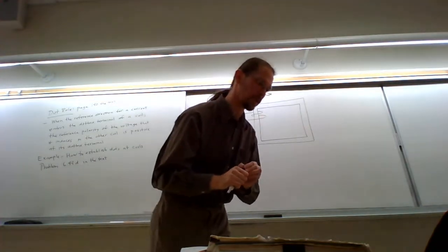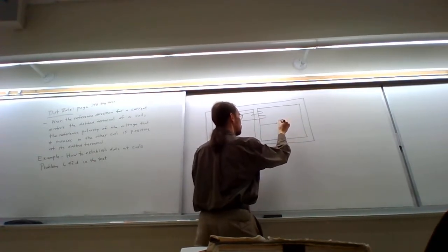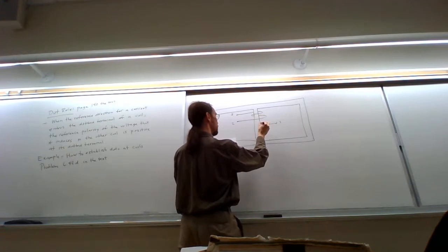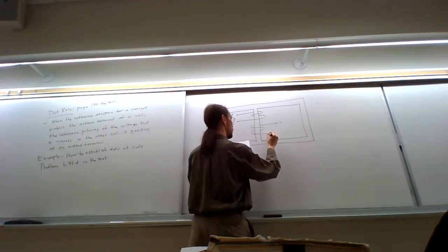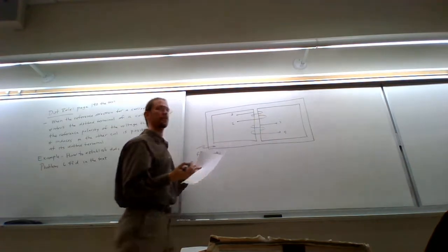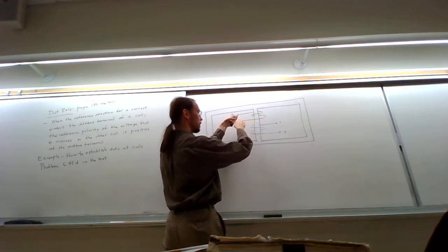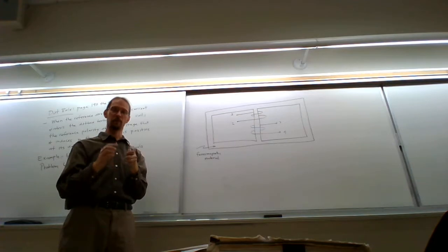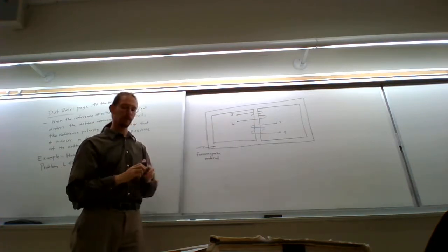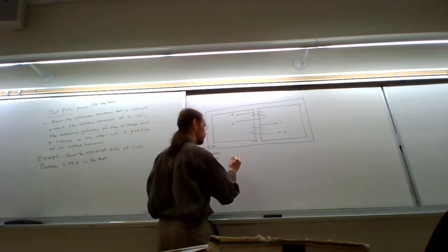There's a second coil, or a second inductor, where we have our third terminal, and this goes around the back, comes back around the front, goes back around the back again, and then comes out the front like so. So here we start with our wire and then we wrap it around like so again, right? So here we actually have the physical windings of the coils. This particular structure is relatively common. It's what they call a shell-type transformer.